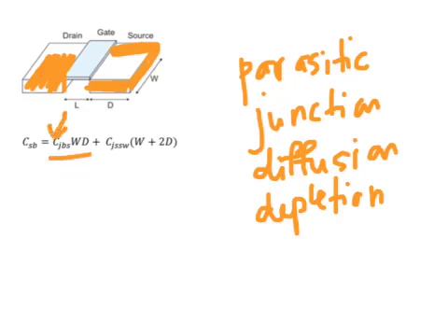And so the contribution to the junction capacitance from the bottom plate is this part here, a normalized coefficient here, multiplied by the width and the length of the end doped region. So that's the area here, as well as the total perimeter, that is the width and twice the length of the region, because we're going here, here, and here.